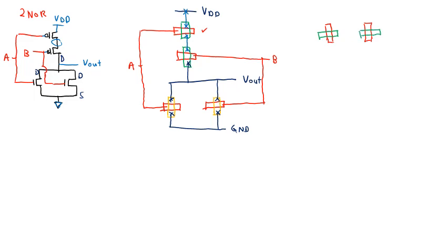And you also have the NMOS. You rotate the NMOS polysilicon. You have this and this. I just want to put it aligned to the PMOS. And then we have to rotate the N diffusion here and here, right?